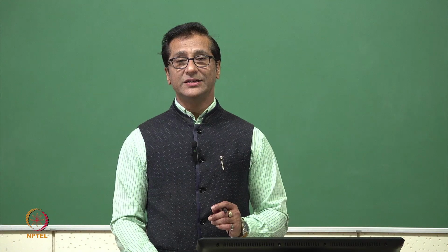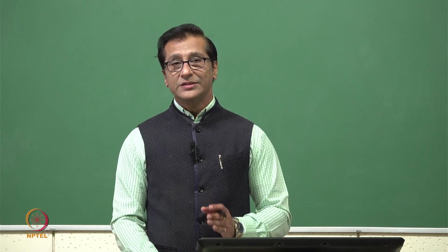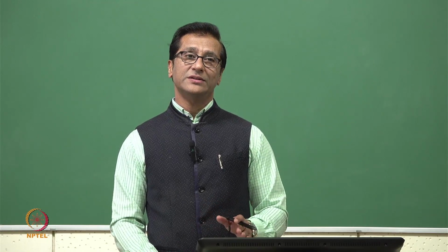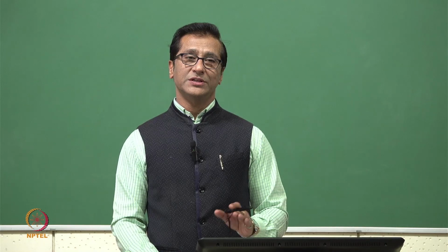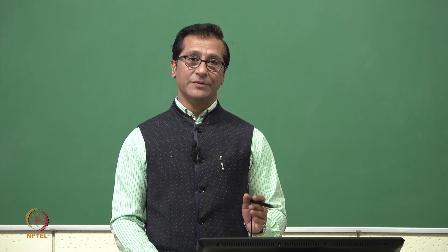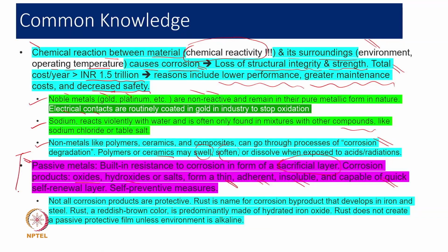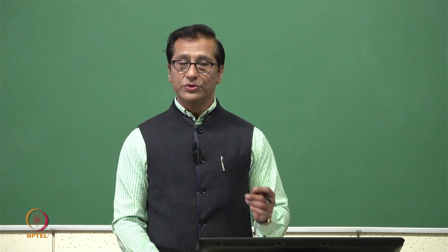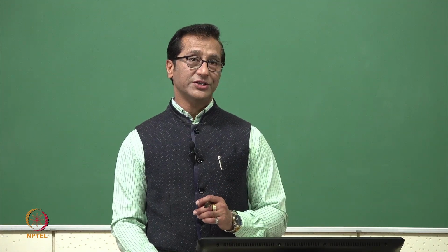If the layer is getting dismounted, removed or scratched, then there is a possibility the layer gets reformed or renewed immediately, that is, self-healing capabilities are there. If this kind of material is available, then it will be very useful, and we should use it. However, it is also known that not necessarily whatever oxide formation or corrosion product occurs is protective in nature.